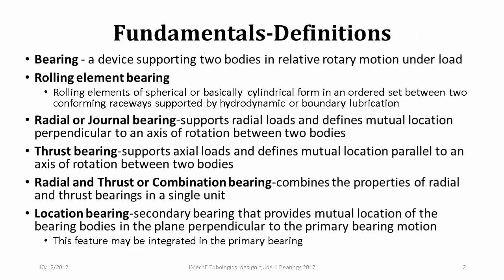So some fundamental definitions. What is a bearing? A bearing is a device supporting two bodies in relative rotary motion under load. A rolling element bearing has rolling elements of spherical or basically cylindrical form in an ordered set between two conforming raceways supported by hydrodynamic or boundary lubrication.